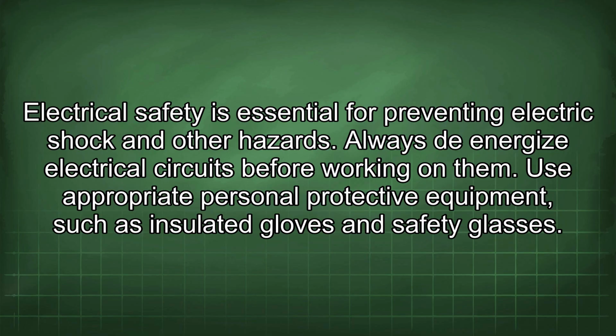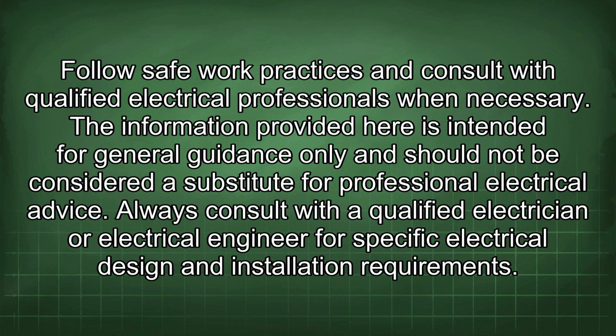Electrical safety is essential for preventing electric shock and other hazards. Always de-energize electrical circuits before working on them. Use appropriate personal protective equipment, such as insulated gloves and safety glasses. Follow safe work practices and consult with qualified electrical professionals when necessary.